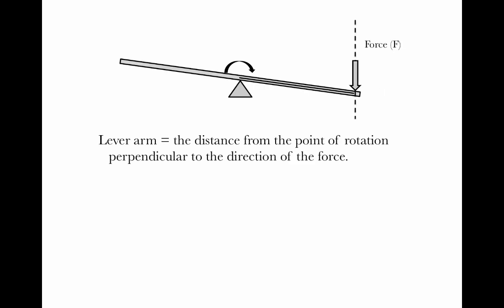When we rotate, this changes the properties of that lever arm. Remember, it's the perpendicular distance to the application of the force. So we need to make sure that we're measuring our lever arm perpendicular to this line of force. If we extend that force with a dashed line, this would be our line of force. Now we've got a lever arm that is a little bit less than just the straight distance along the lever from the center of rotation to the application of the force. It's going to be a little bit smaller, and we can compute mathematically what this would be using simple trigonometry.